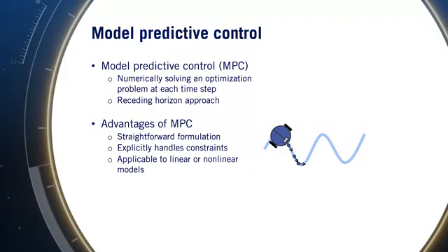The states and control signals can be constrained to stay within safe operating bounds, and controls can be selected to maximize multiple objectives simultaneously. Both hard constraints and soft penalties can be employed, leading to a rich set of solutions for constrained control problems. As many automotive subsystems have rigid actuator constraints and diverse performance objectives, MPC has emerged as a major tool for vehicle control. The controller can be explicitly applied to the linear or nonlinear models of the vehicle and its subsystems, meaning that we can use the same approach even as our models change or improve over time.